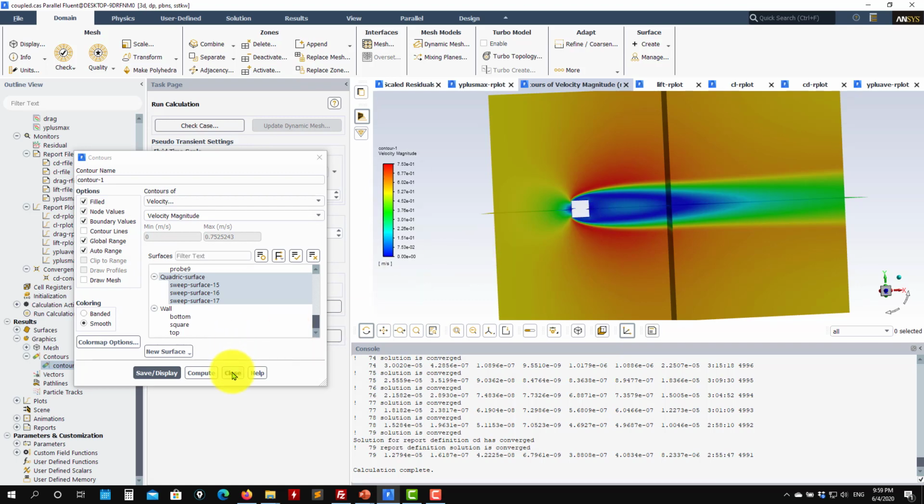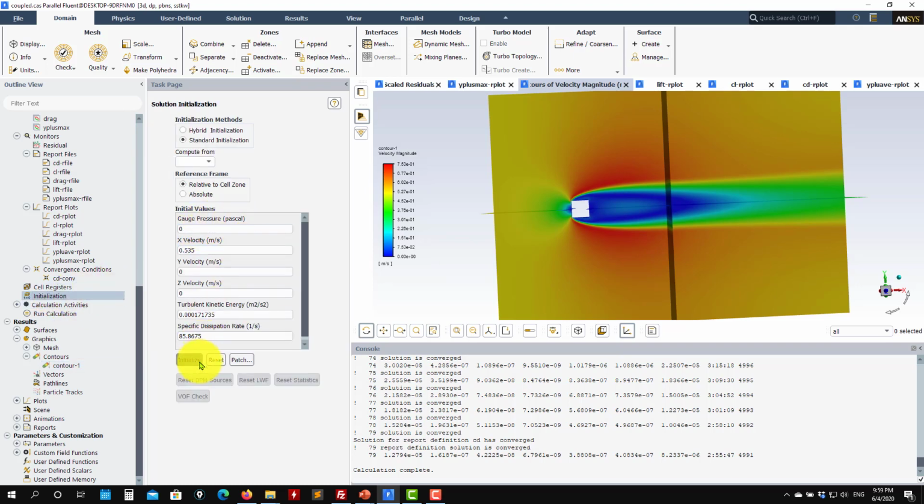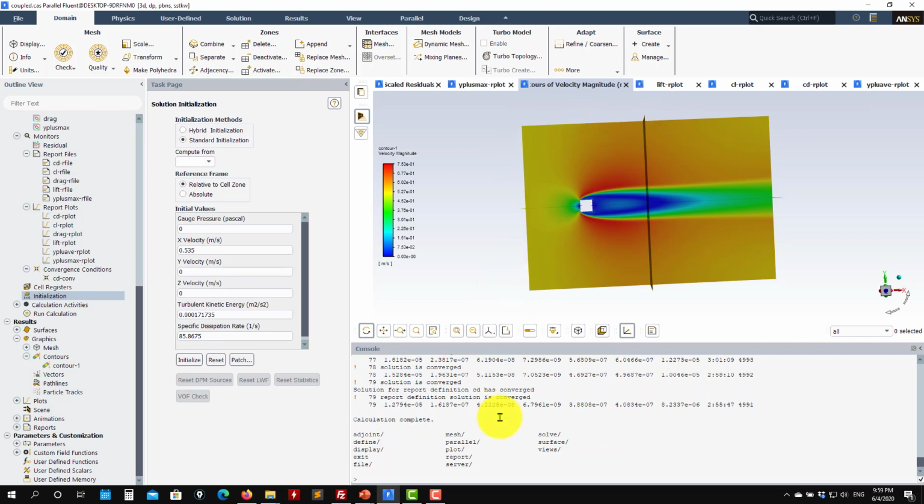So let's change now and rerun, but using non-uniform initialization, the full multi-grid. So let me initialize again. Okay, so we go to 0. By the way, see that here we have state wall. So in the initialization, you will probably see that you have a boundary layer, but then when it runs, you don't have that effect anymore.